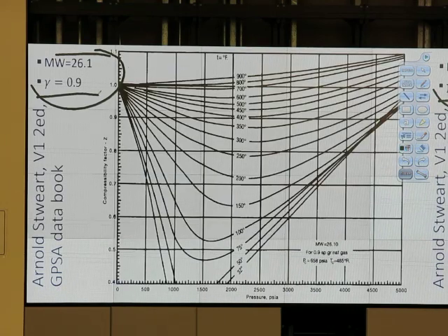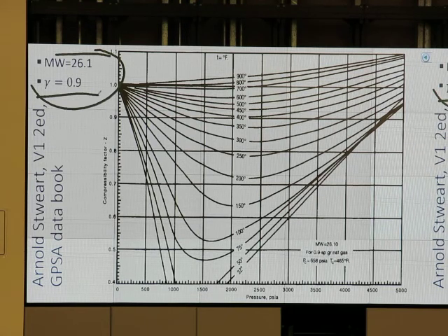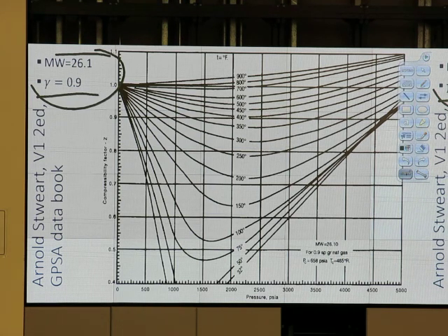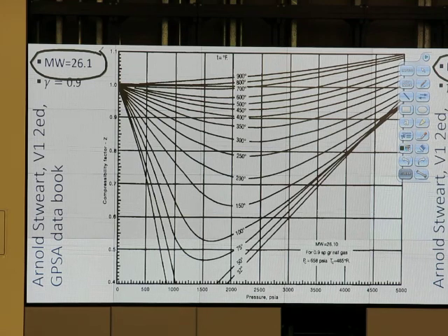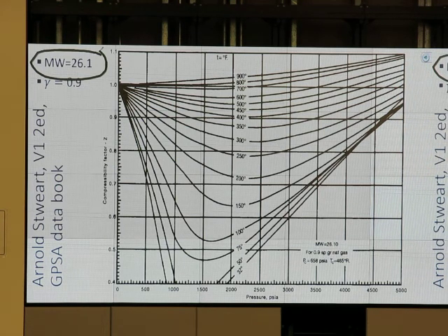How do we get the molecular weight of the gas, or the average molecular weight of the gas? If the gas is just a single component, we know it right away, right? But it can be many components. For the case of many components, Rohan, yes. What do we do? How do we get the average molecular weight? We get the average molecular weight based on the concentration multiplied by molecular weight. Concentration, mole fraction. Yeah, weighted by mole fraction.